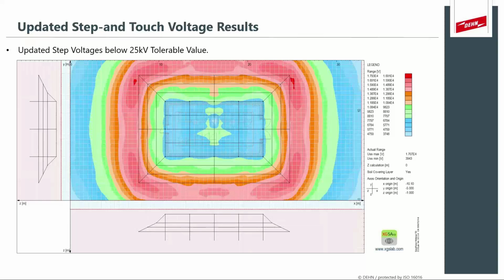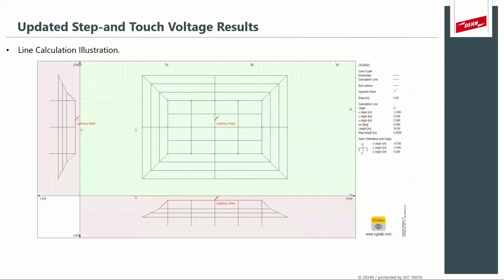Now, I mentioned briefly that we use the high frequency components, in this case 250 kilohertz, to give graphical images and nice views of how we describe ground potential rise. But the correct manner is to use an impulse, which we describe to be a 1,8 by 285 microsecond impulse. To do that, the software then breaks that impulse up into a set of frequencies. In this case, I chose 167 different frequencies.